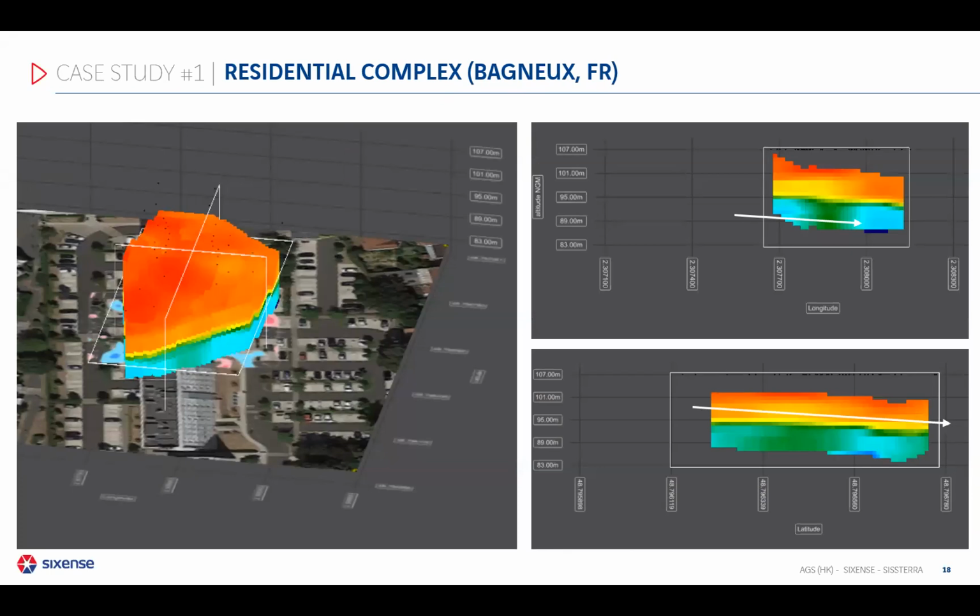The result we obtained after listening to the noise and processing the seismic signals is a quite simple 3D model of shear wave velocity that revealed 2 layers of different stiffness, of different shear strength, and competent materials. So the second layer was found at different depths across the building, ranging from 5 meters depth in the northwestern part of the model to 10-15 meters depth in the southeastern part of the model.